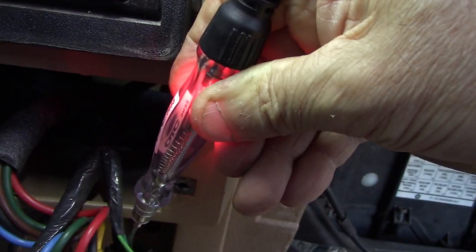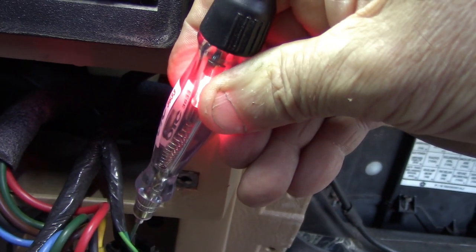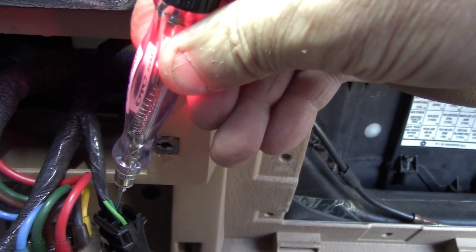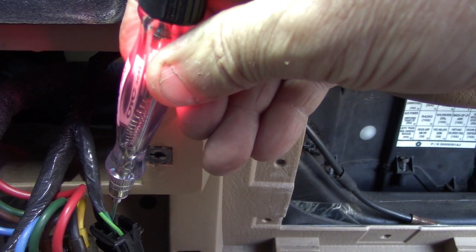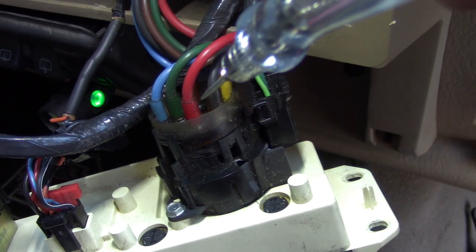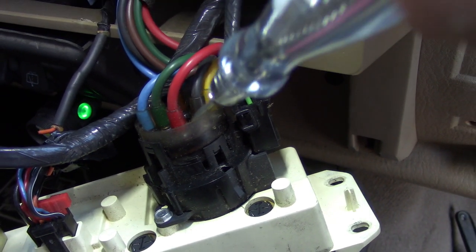All right, now back in on the back side of that green wire is the ground wire. Okay, I'm providing power to the ground wire. My test light is lit. That means I have a ground. Now, there's something said about carrying a load, but I don't want to get too technical. All right, the ground appears to be good. I have power to that switch, and I have a good ground. So the only thing that possibly could be is that switch.